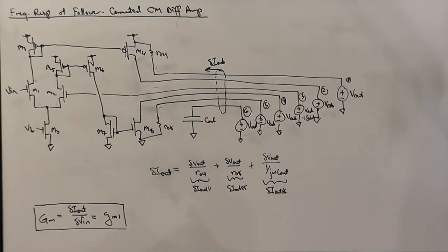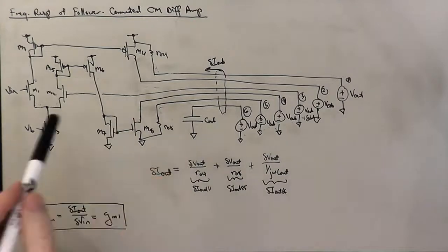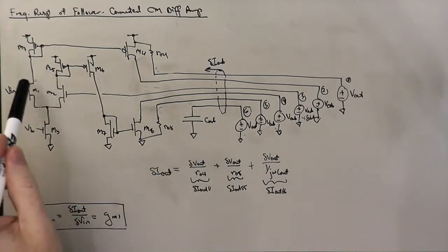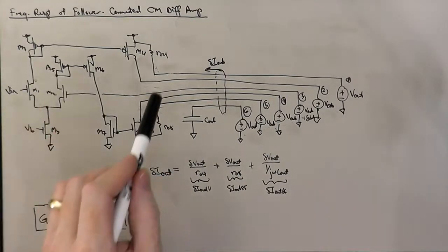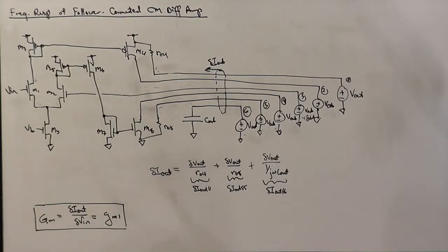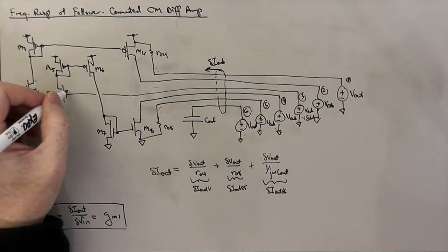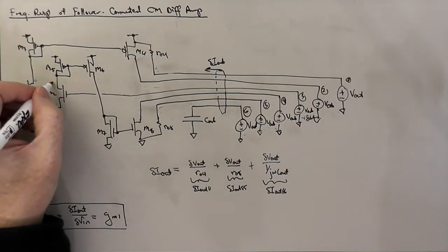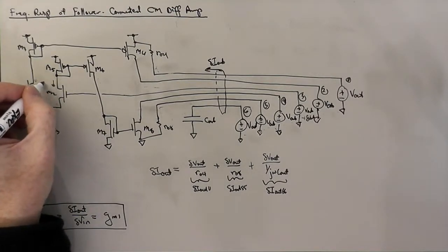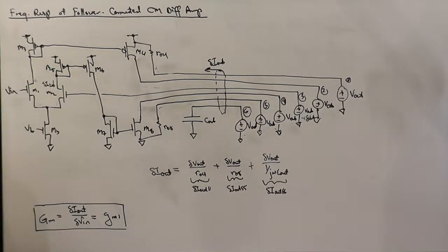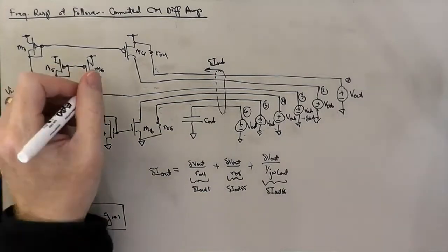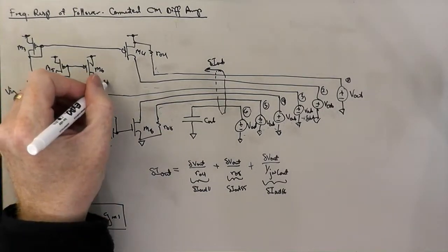Only now we split the source, and the two different effects as we go around different pathways in the circuit are going to come out in different branches. So we're increasing the current in M2. So there's a delta I2, and that's going to do 2 things. It's going to be mirrored by M5, M6, delta I2.